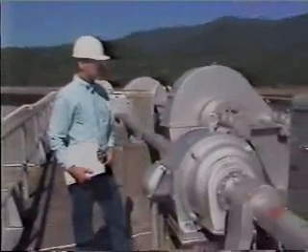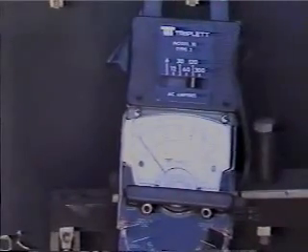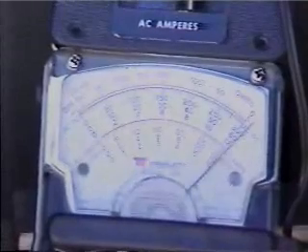If the motors sound like they're straining against the load, or if you hear unusually loud humming or squealing, problems may exist. Another way to tell if there's a problem is by checking the voltage and amperage readings during startup and normal load. If readings are taken at the time of the inspection, compare these with the past readings.